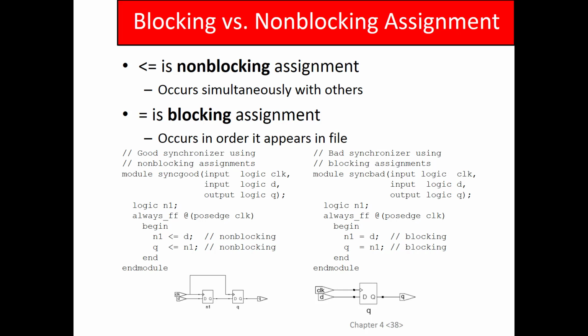But as I was saying earlier, this behavior extends beyond a single always. It actually has to do with the event that triggers the always from executing. So in other words, imagine I had two of these always blocks, and in one of them I just had the first line of code, and in the other I just had the second line of code. It would still produce the same behavior. They would both basically collapse into one flip-flop.